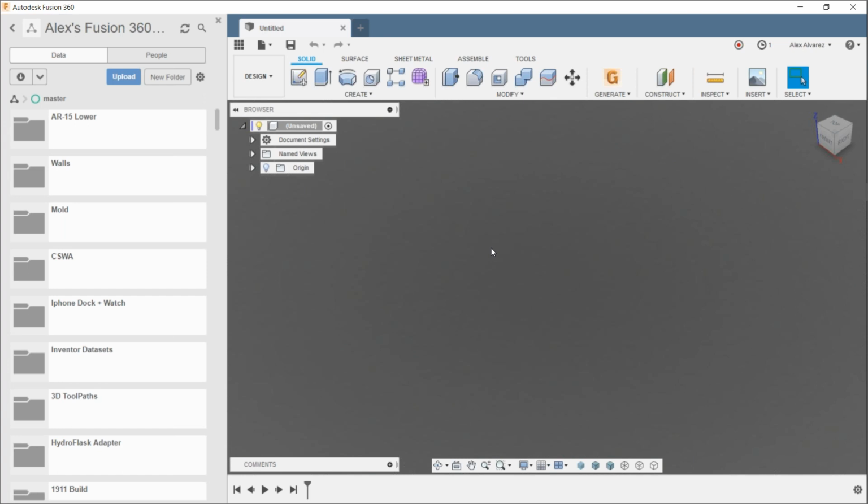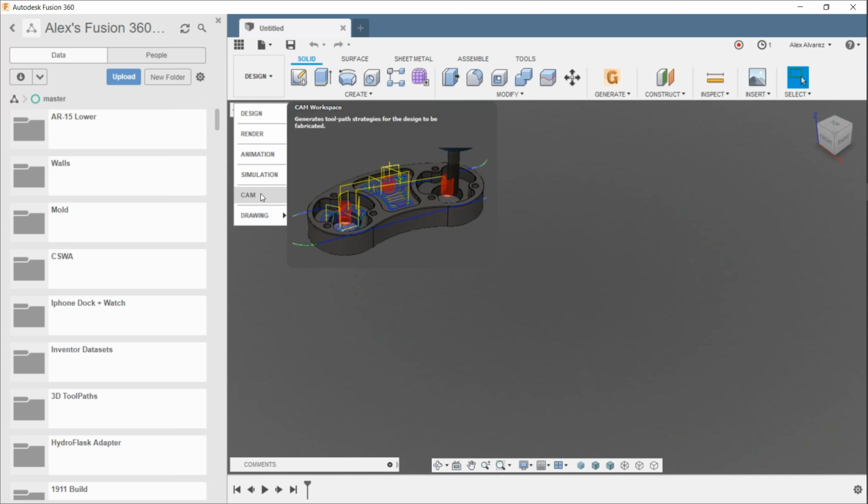What you can do is use that circular pattern and then post out to your machine. Especially if you have the HSM Ultimate or Fusion 360 Ultimate, and you want to pattern that, and you have fourth axis capabilities, you don't have to necessarily use tool orientation for each individual one. Just use a circular pattern and then post out to your machine.